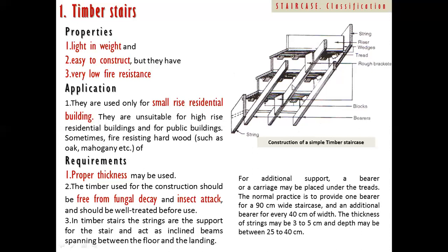To connect the bearer and the tread, there are blocks, which are nailed to the tread and riser through the bearer. The strings are the most important assembly part of this timber staircase, as they give a position to rest the tread and riser, generally placed at the edges.